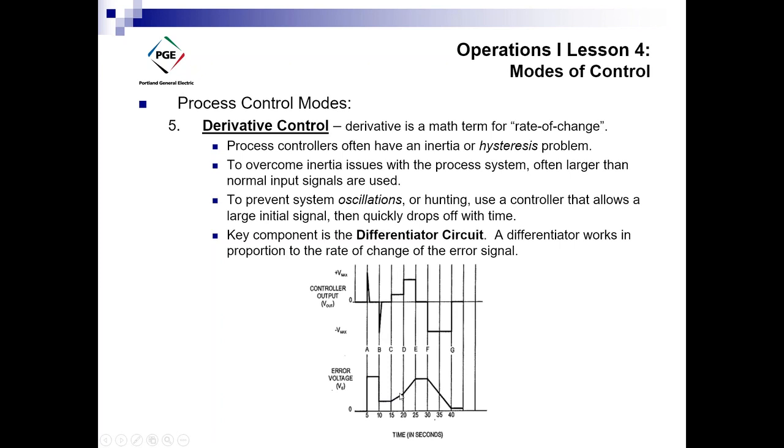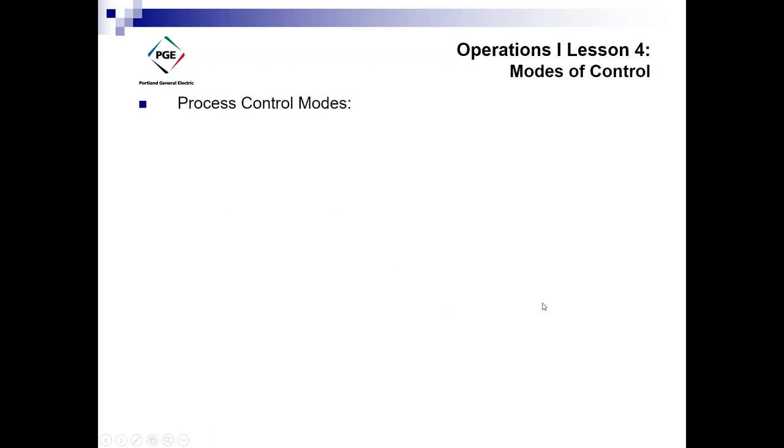And you can see you just keep going here. So you get another spike from this. See, this is not a rapid change. It's more like a slow increase in the error. So that kind of shows you how, with the change in the error signal, how the controller, the derivative controller, will output that. So if the signal's not large, the controller output may change not as rapidly, or may just change to a new level and be steady state. I hope that makes sense.